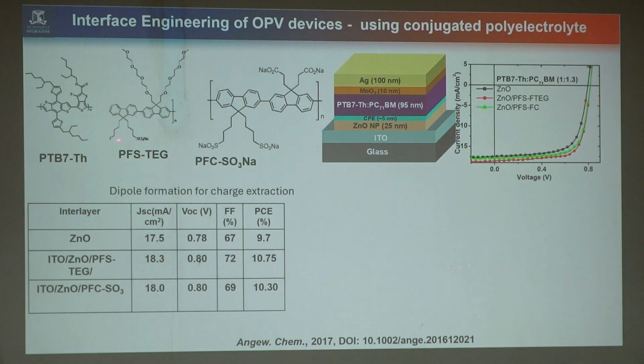These are sulfonated sodium TEG, and we have multiple oxygen groups. These multiple oxygen groups make it more hydrophilic. This type of functional group will induce a dipole on the surface. The more dipole, the more electron-rich the compound, which helps as an electron extracting layer.